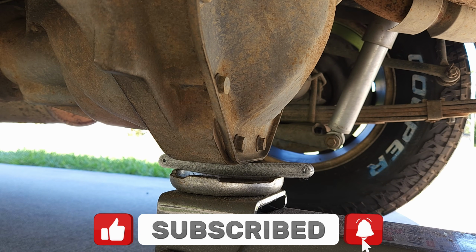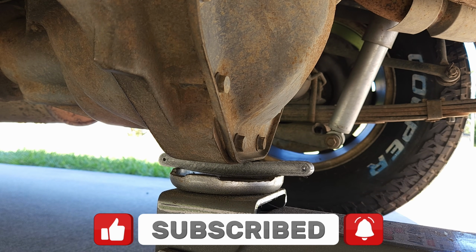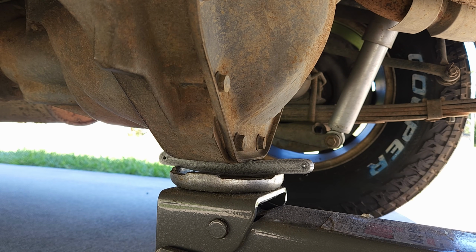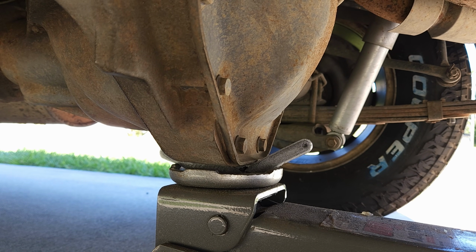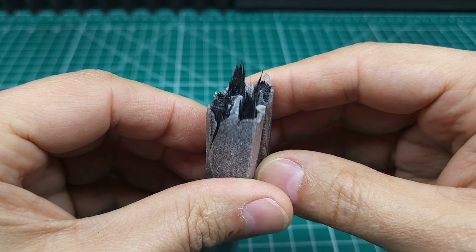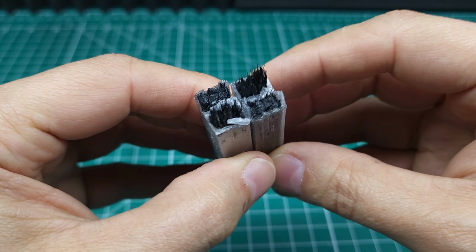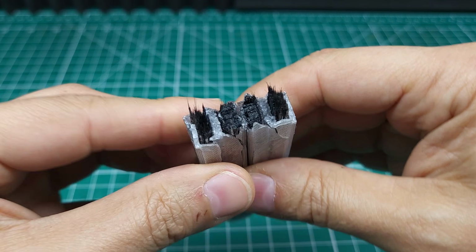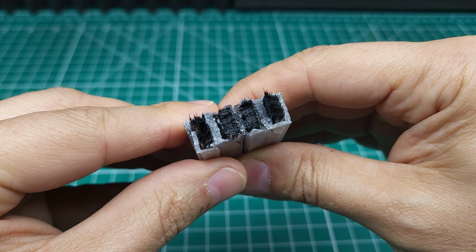We're definitely taking some good weight off the truck here, but you can see it's really starting to flex. All the weight is still on that bar though, and we are actually almost, and there it goes, okay. Though I have no way of knowing exactly how much weight that held, based on my experience, it felt like it was about halfway up, which means this was probably holding close to 1,000 pounds. And you can see it just shattered right through those carbon fiber strands.